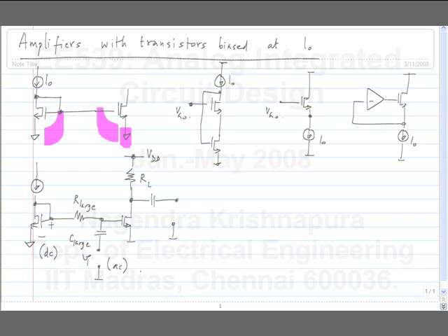So the resistance and capacitance are large. I mean large meaning they are large compared to whatever things are connected in series, and also at the relevant frequencies. So you should be able to calculate the values of R large and C large given the frequencies of interest and the bias current I0.